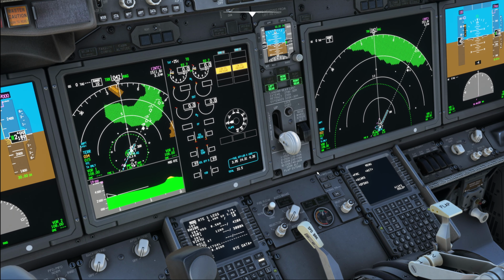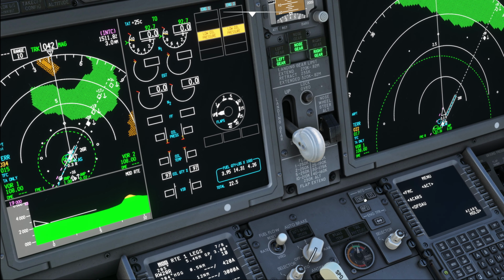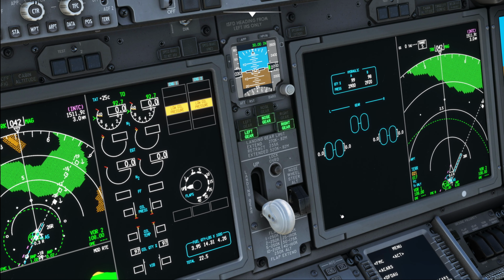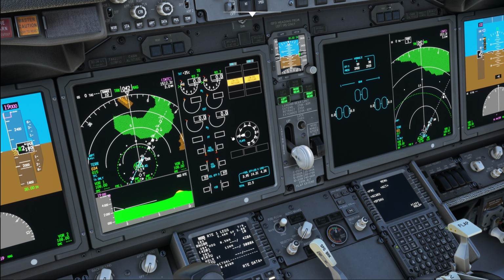And then we are going to go up to the MFD switching over here. While we're at this, we are going to select the system display and ensure that any indication over here is normal. So the hydraulic quantity is not showing the RF indication, which would stand for refill, happens at 70%. We ensure that we have positive hydraulic pressure, and if we are equipped with the brake temperature indicator or brake pressure indicator, we would also check for those. Then we move on to the ICAS and check the oil quantity to make sure that we have sufficient oil quantity on board here as well.